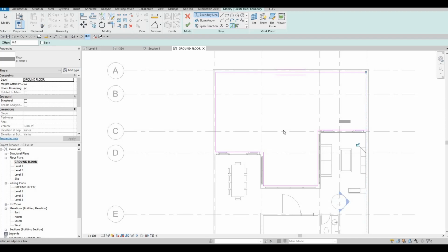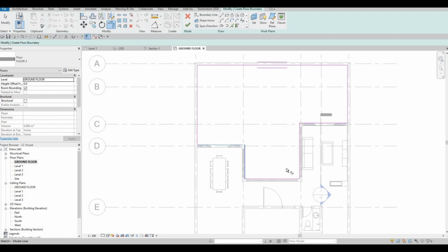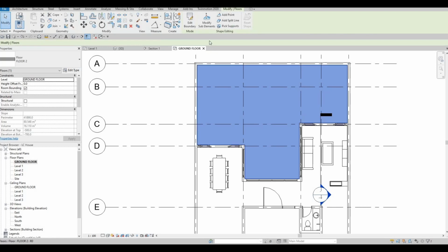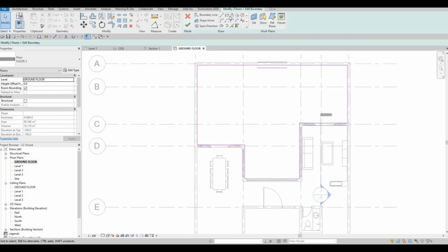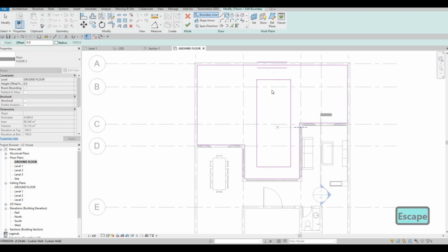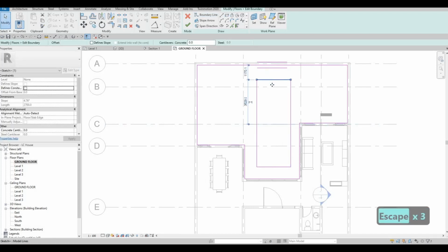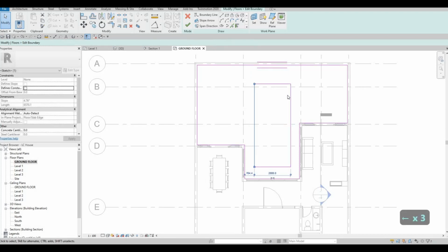So before we click on finish, we're going to create a hole on this side. So TR to trim and extend everything, make sure everything is lining up, and just click on finish. And then actually, before we click finish, let's edit that again and then click on rectangle, and we're going to add in the pool. I want some space to go around here, so not pushing it too much on the space.